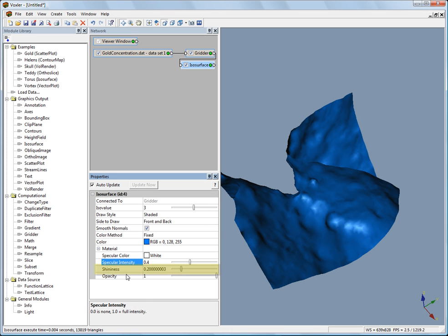The Shininess option controls how shiny the surface is. Larger values display smaller and brighter, more focused highlights. Smaller values display less focused, larger highlights. To change the shininess value, click on the dragger and drag it to a new value. Alternatively, highlight the existing value and type in a new value. The values range from 0 to 1.